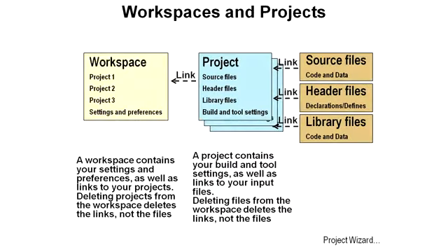To understand Eclipse workspaces and projects, when you work with Code Composer Studio and Eclipse, you want to create a workspace to work in. A workspace will contain your settings and preferences that you use for Eclipse, as well as links to your projects, not your projects themselves. So here you can see we have projects 1, 2, and 3 in there, all the settings and preferences, where we put the windows, how many different perspectives that we have. This way you can delete projects from your workspace by deleting the links, not the files themselves.